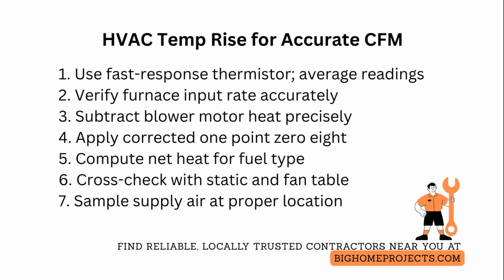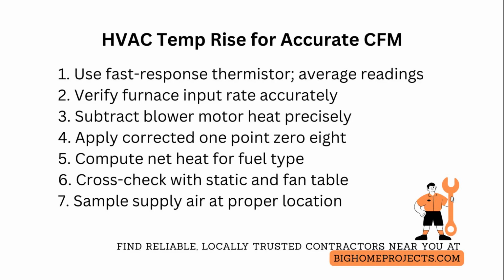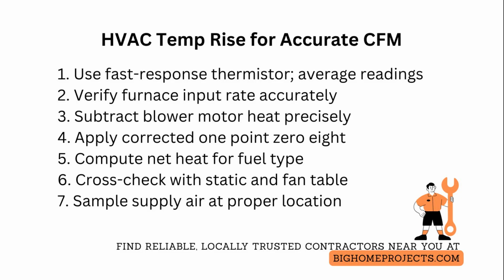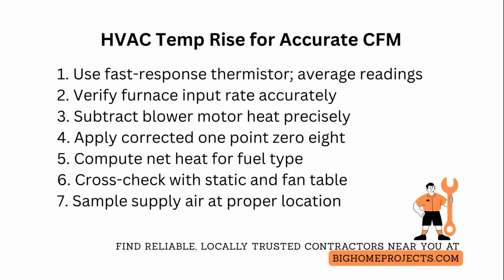For electric heat, net heat in British thermal units per hour equals kilowatts times 3,412 minus measured motor wattage. For gas, net heat equals actual input times combustion efficiency times heat exchanger transfer efficiency verified by steady combustion analysis.